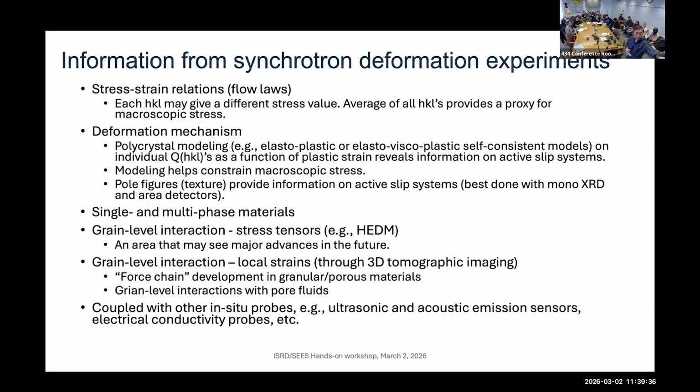And of course, all of these can be applied to single crystal or single phase or multi-phase. You can take different phases in the sample. And since diffraction is so powerful, you can actually pick out which peak belongs to which phase, and how they deform, what kind of mechanism they have.